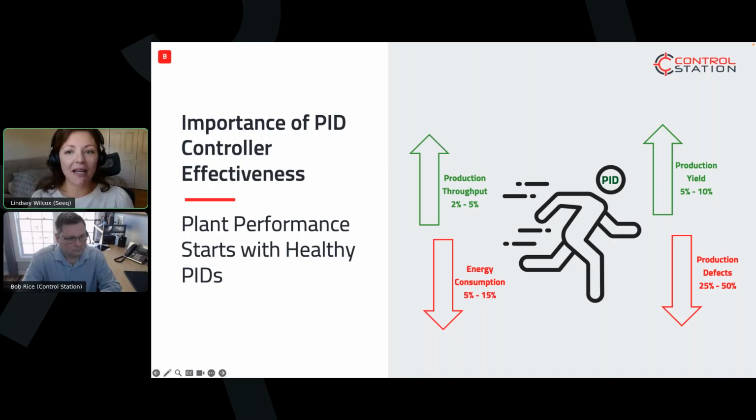It's making those split-second adjustments in the process to control temperature, flow, pressure, whatever that process variable is. And as you said, with your example, when everything's well tuned and operating well, we're happy, the process is smooth. But on the flip side, when we have poor tuning or interactions, oscillation, poor strategy, the whole process can suffer, and we see those issues cascade throughout.